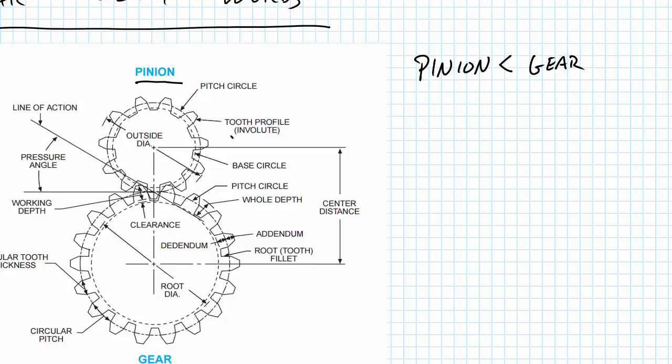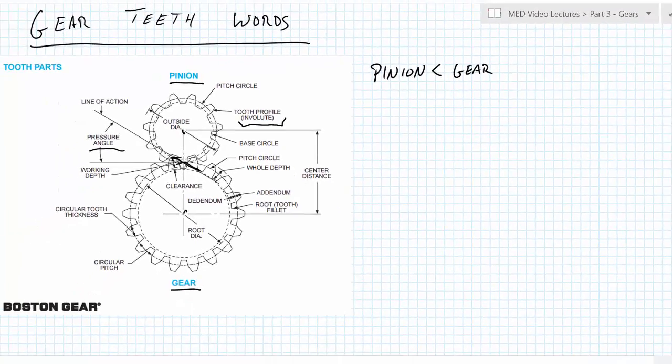Second, a gear tooth profile is that involute shape. It is that involute shape riding on another involute shape which gives us our conjugate action, a smooth transition from one to another. And that action happens along a particular line. So this line is defined by a pressure angle from the tangent of those two gears. So if you make a line between the center to center of the gears, a line that is perpendicular to that will have a pressure angle defining how those teeth interact. So there's a particular angle here, and that angle, of course, is going to determine how much of the force goes into turning the gear and how much of the force from that torque goes into pushing the gears into each other. And those forces of pushing into each other are then, of course, resisted by the shaft and the bearings which support them.